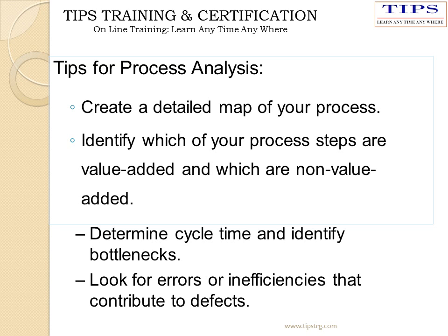For that, you have to follow these things. After creating the detailed process flow chart, now identify the process stepwise for value added activities and non-value added activities. Determine the cycle time and identify the bottlenecks for this process.